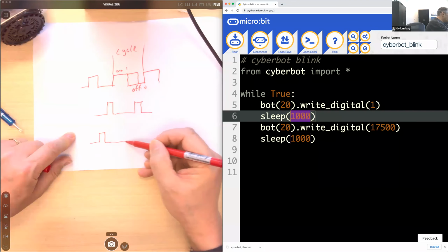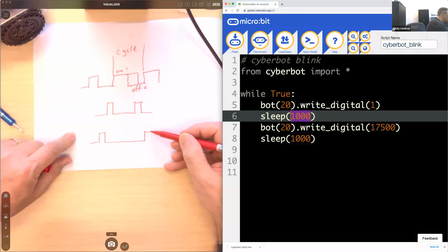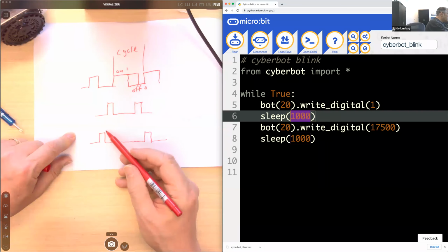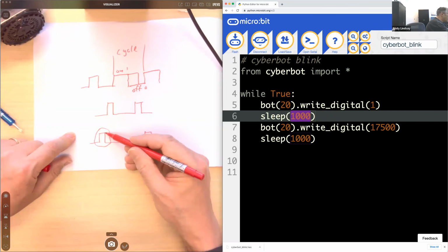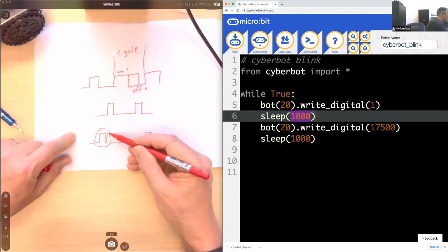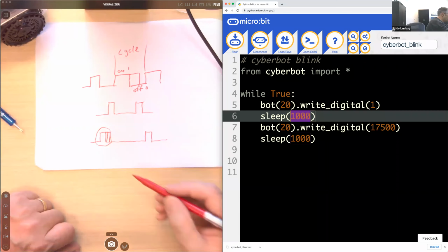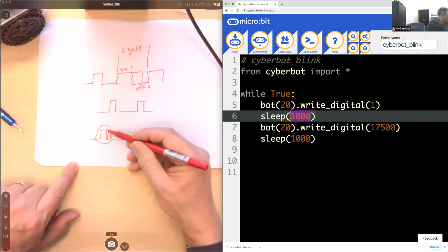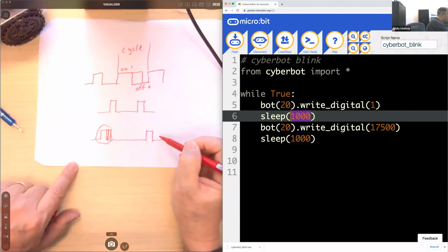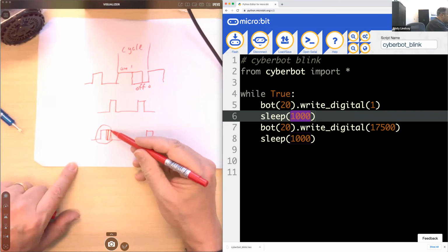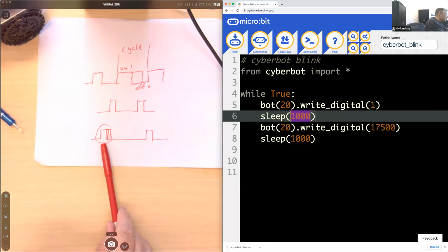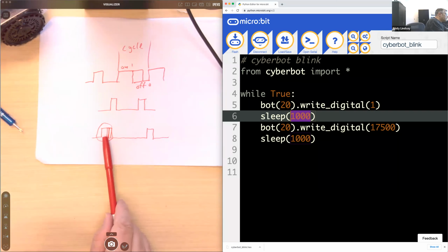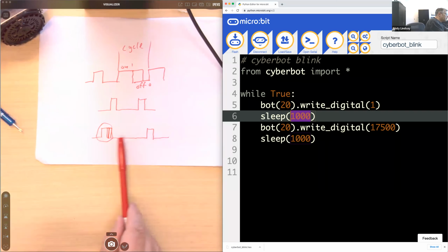The servo control signal, I think I showed that earlier on. What the servo pays attention to is the duration of that pulse. And it's only a little longer to make it stay still and a little longer still to make it turn counterclockwise. So if this was a clockwise signal starting out, you make it longer and it has to repeat 50 times a second. It might stay still. And if you make it longer still, I'll get back to this. But the idea is that there's 50 pulses a second, and each pulse is a specific amount of time, and that controls the servo speed and direction.